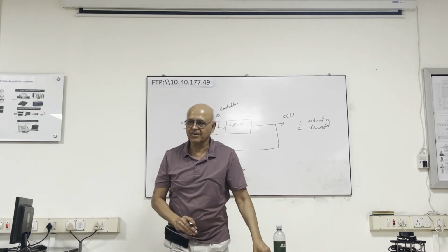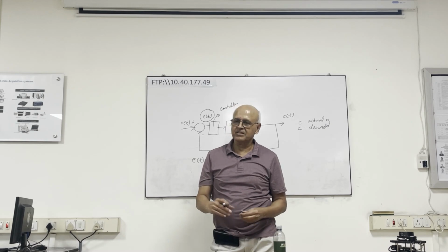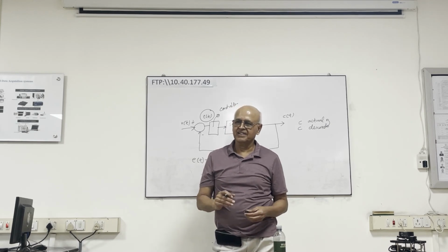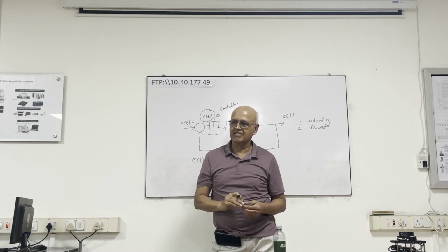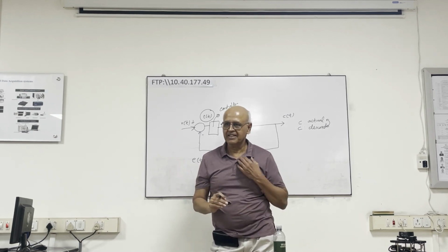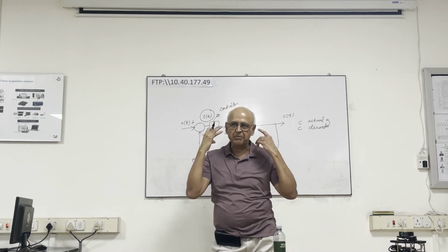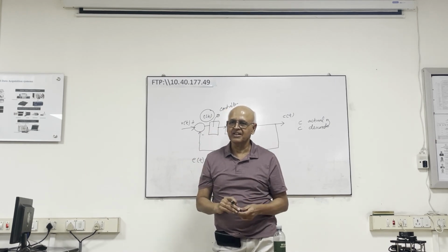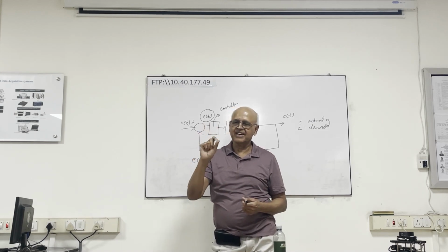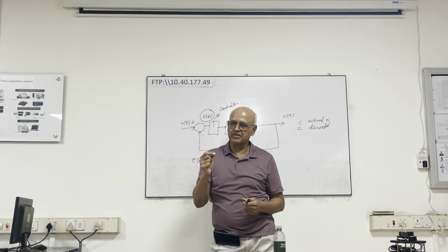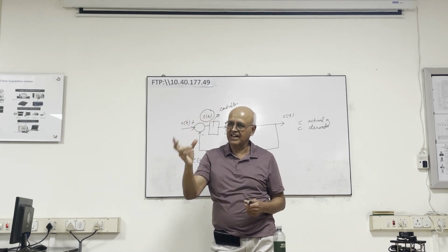If you have a closed loop control AC system, at night when you reach the target temperature, it will turn off for a while, right? And then it will come on again. So there's a little bit of oscillation of the error signal. You know what I'm saying? Yes. But you don't want to have it turn on and off all the time because you'll go crazy. You won't be able to sleep. So they have methods to create a dead band so that it doesn't turn on immediately. It allows the temperature to go a little bit below and a little bit higher. The two thresholds are triggered at different times.